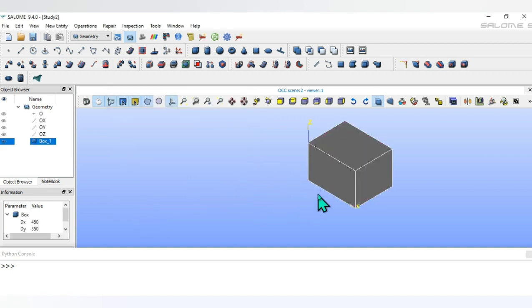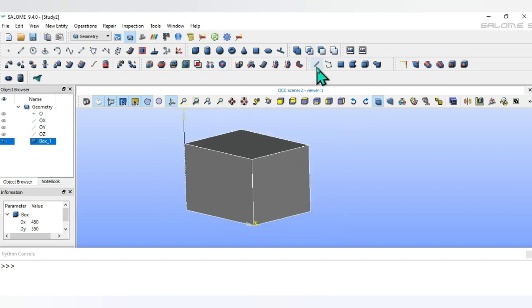Okay, right. So now you have your box. Now this is a solid body. How do I know it? Well, if you see this panel over here, you have edge here, and then you have wire. Wire has got points as well along with the edge, and then you have face. And when you combine a few faces, you can make a shell out of it. And when you have a closed shell, you have solid. And when you're combining two solids, or one solid and a shell and stuff like that, that's compound. That's the hierarchy which you need to really understand, because if you understand this bit, then whatever is happening in your tree, you'll be able to get it very nicely. So I repeat myself: this is the edge here, and then you have wire, and from the wire you can create your face, and when you combine a few faces together, you can have any kind of shell, and then you can have solid and then compound.